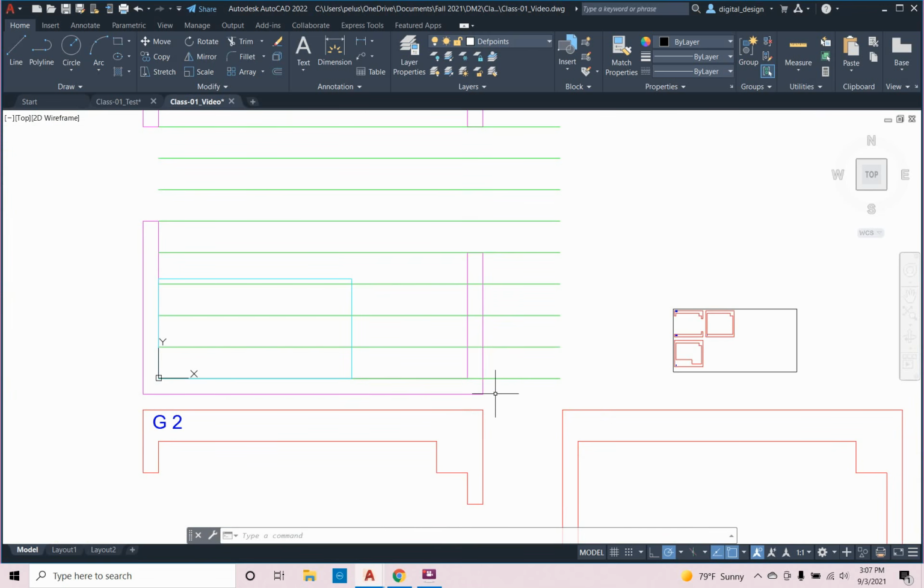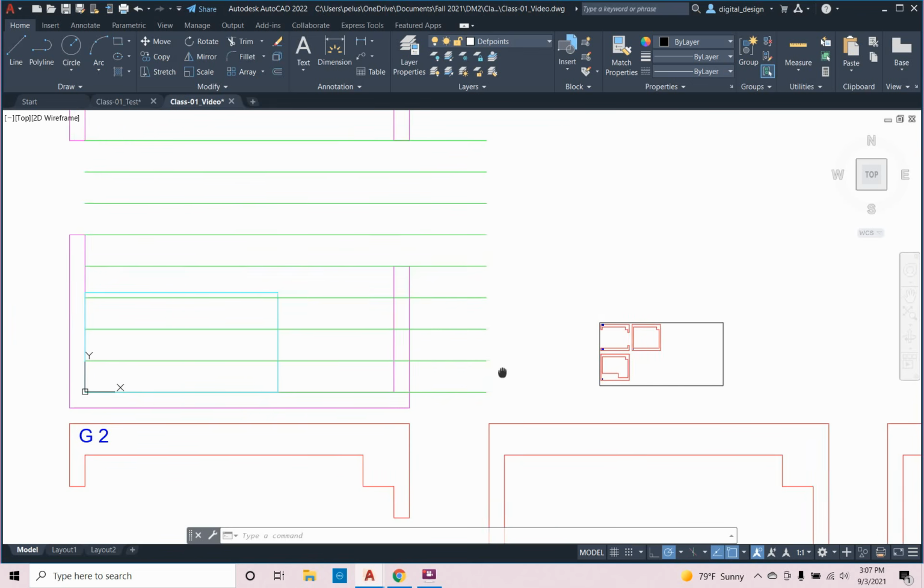So at scale, that's at 1/2 of an inch. Okay, 1 inch equals a foot. So these are all at a foot apart. These sections will all be spaced at a foot, which is 1 inch at 1 inch equals a foot. So these will all be placed at 1 inch apart, and the first one's at 1/2 inch.